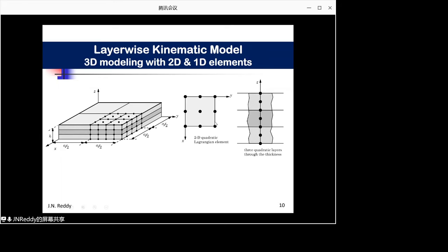Similarly, for the second case, where the 3D element uses quadratic in the thickness and quadratic in the plane, again you see it takes 1,182,000, whereas the layer-wise theory only takes 284,000. So this tells you that computationally the layer-wise theory takes less computational time, but produces exactly the same results as 3D because it is 3D. It has the same displacements as the three-dimensional solid. However, the layer-wise elements are only good for laminated structures. You cannot use them for an arbitrary solid because there are no layers.